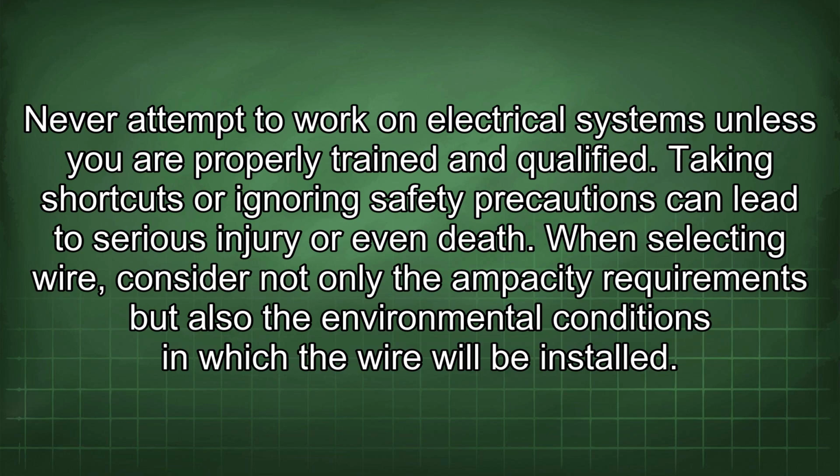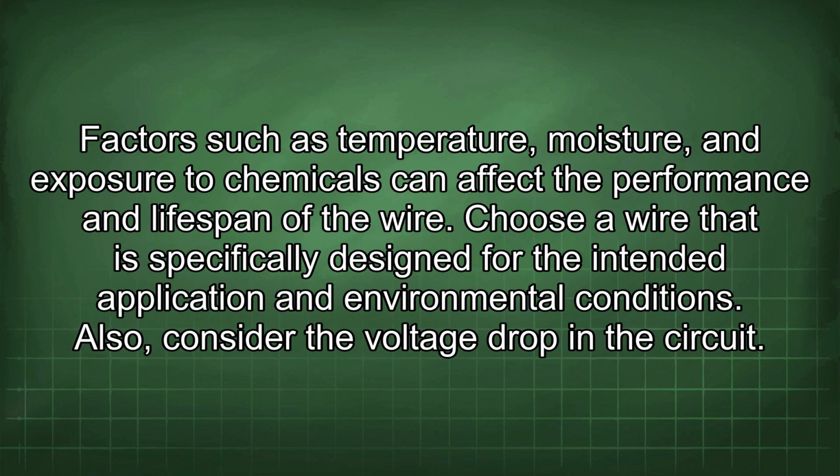When selecting wire, consider not only the ampacity requirements but also the environmental conditions in which the wire will be installed. Factors such as temperature, moisture, and exposure to chemicals can affect the performance and lifespan of the wire.